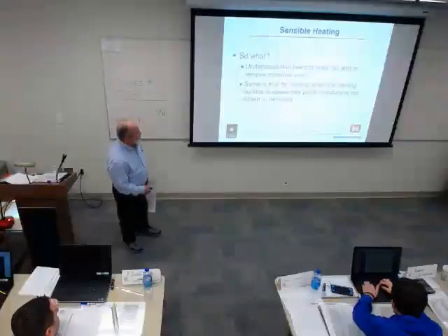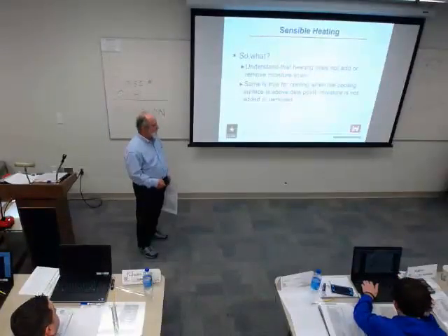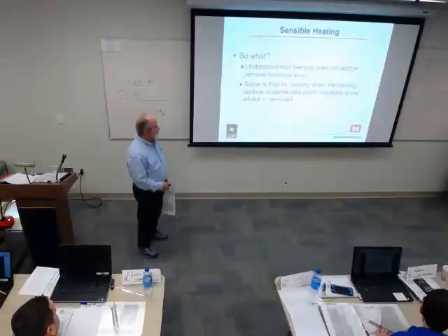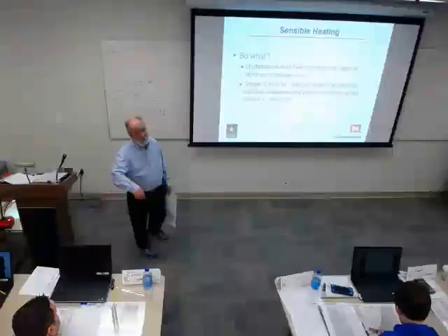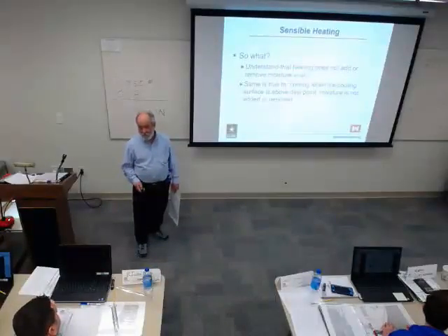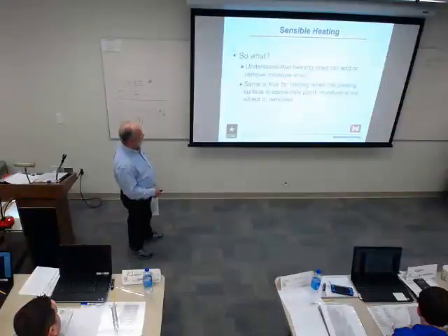So heating doesn't add or remove moisture from the air, and the same is true for cooling when the cooling surface is above the dew point. Most of the time when the air conditions are not, moisture is not added or removed. There are parts of the country, like here, where a good deal of the year moisture is not removed from the air because the air is so dry. Getting into Nevada, some places even more so.